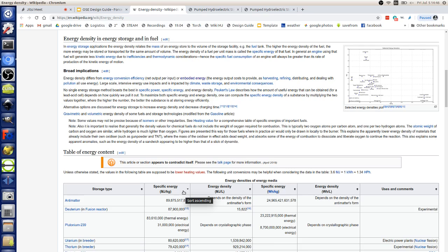So in a day, let's say the 10 or 11 hours, you've got 11 kilowatt hours. That's how much we just said 1 kilogram of diesel has in 1 hour. So you can see that comparison. Solar energy is not insignificant. It's quite significant. Of course, you've got much more chemical stored energy. You can take that 1 kilogram in a bottle in your gas tank and burn it up. For solar panels, you would have to have a big array to trap that kind of energy.